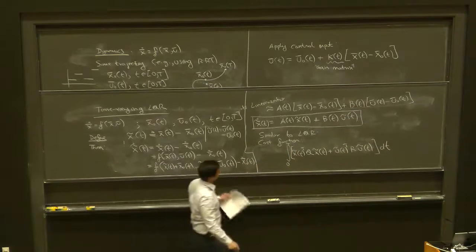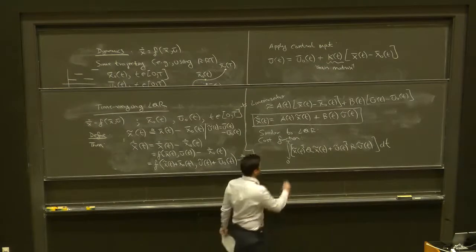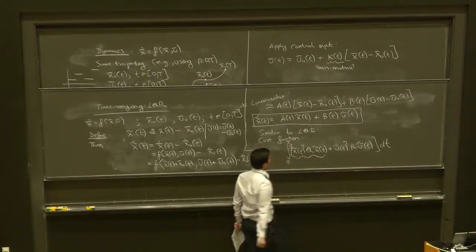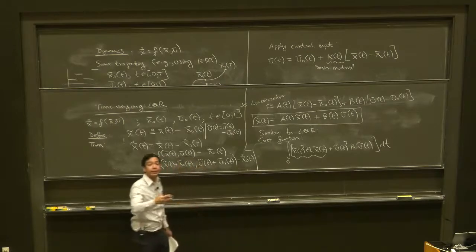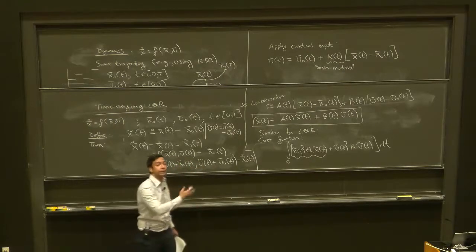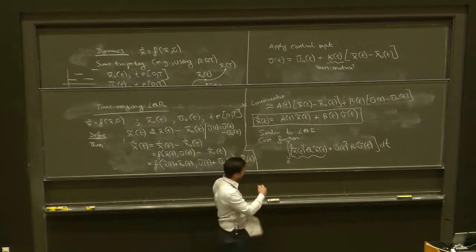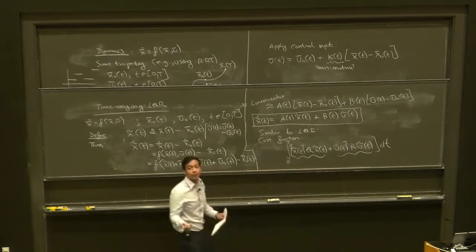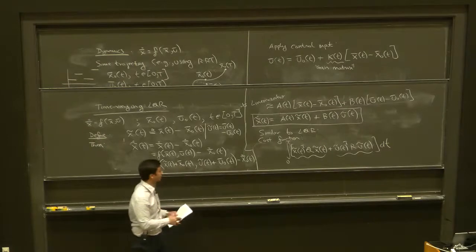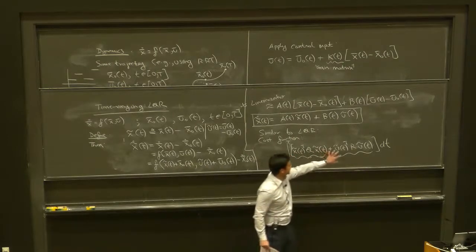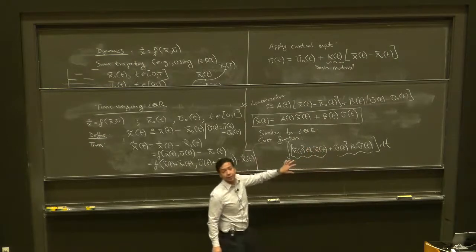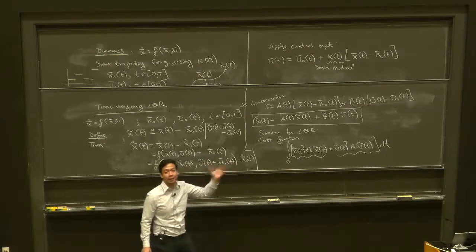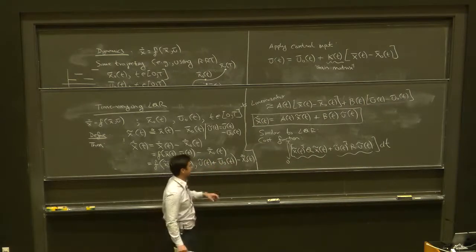This is identical to our previous LQR discussion. This is the penalty for deviating in the state from the reference state, and this is the penalty for the control input deviating from the reference control input. The Q and R matrices are user-defined and tell you exactly how to penalize deviations in different states.